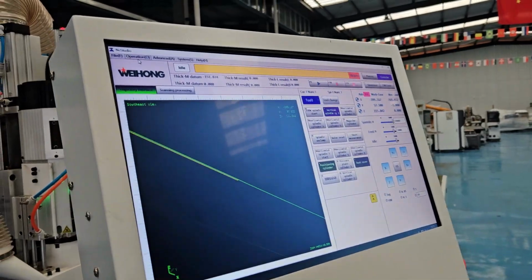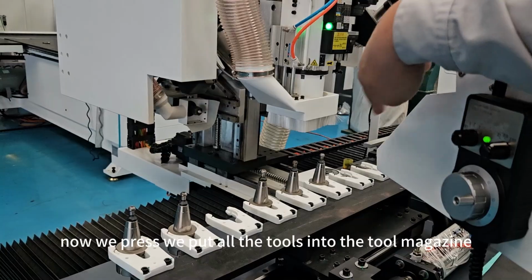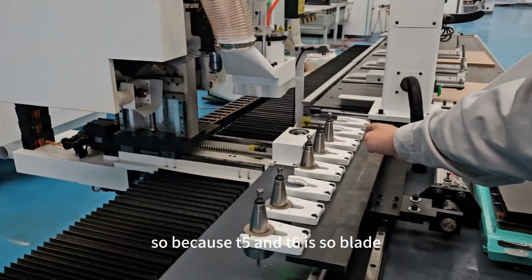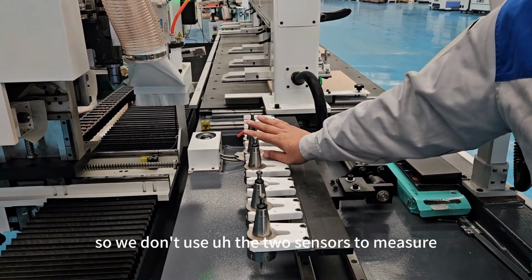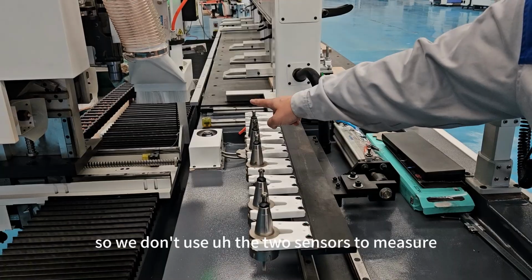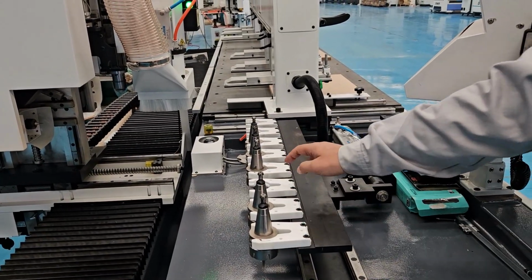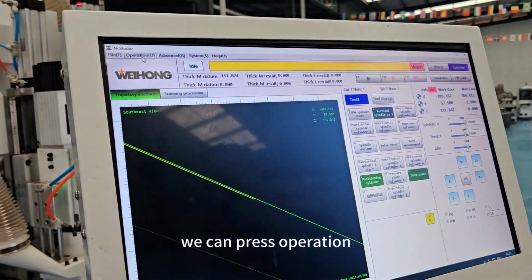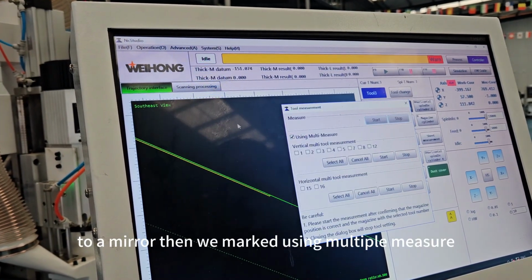So for example, now we put all the tools into the tool magazine. Because T5 and T6 are saw blades, we don't use the tool sensor to measure. So we just measure T1 to T4. We can press operation, tool measure.